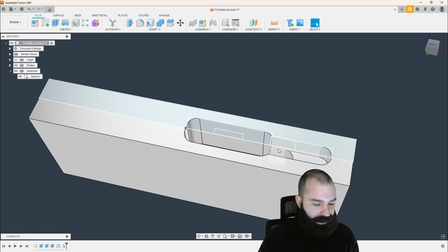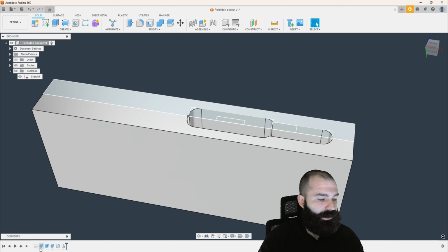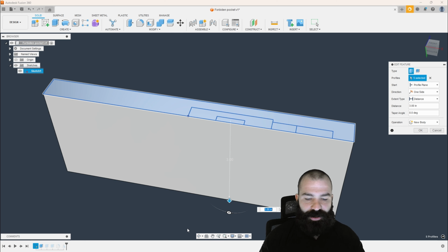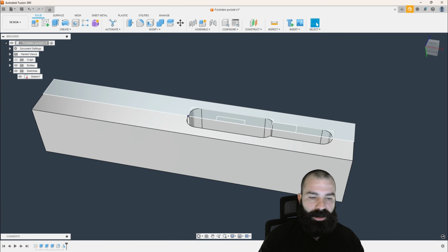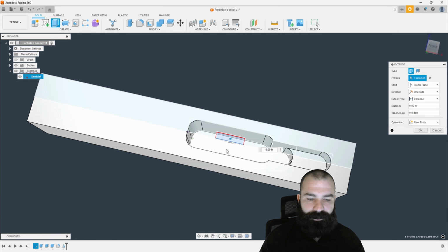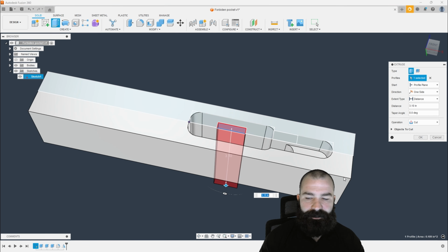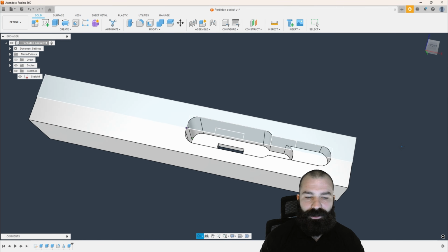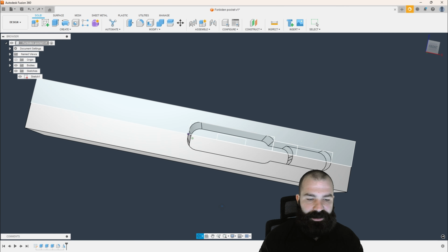And as you can see here, we can actually do a couple of things when it comes to setting that total depth of extrude now, knowing that this is a 1.25 inch pocket. So again, we go back to when we did our initial extrude. I'm going to set it to 1.5. And now I am going to add this extrude where we're going to take this guy here, but I'm not going to do it in this phase. The reason why I'm not going to do it right here is because you're going to notice it only gives me half of an extrude, right? So let's go ahead and Control Z that real quick.